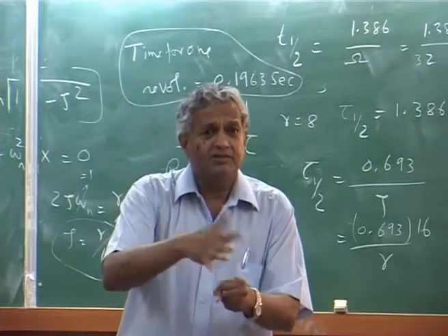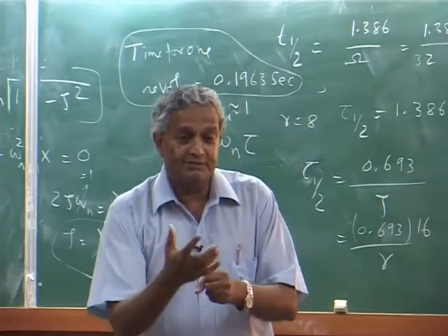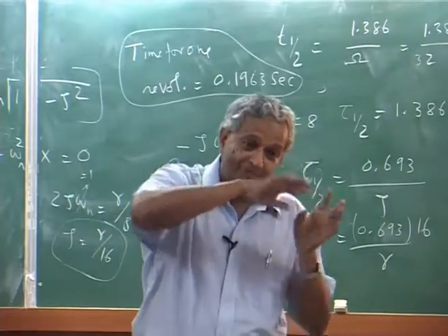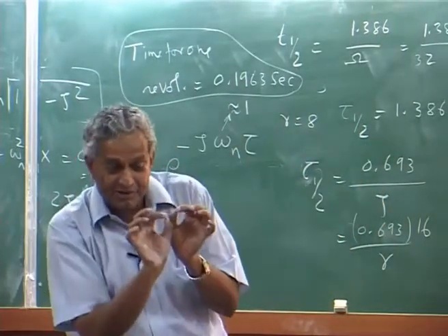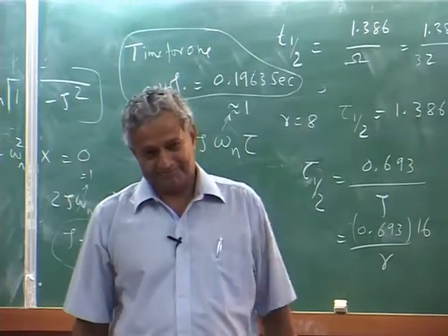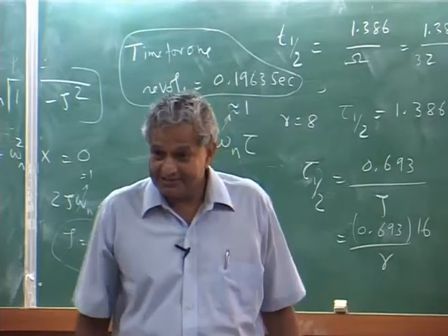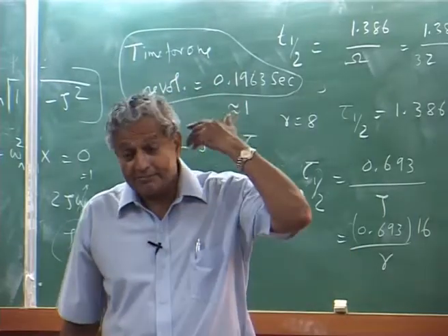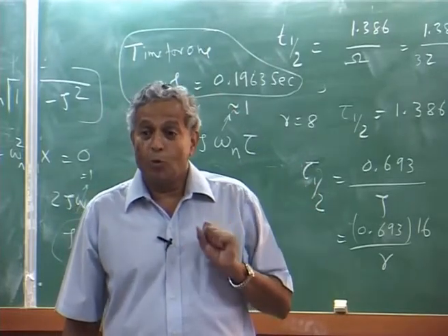Give input, there is a change in force, that is all. How the change in force has happened is because of the dynamics of flap motion, the change is happening over a time, but I neglect that. So when I solve flight dynamics, they neglect even the flap dynamics, in the sense they assume it is quasi static.